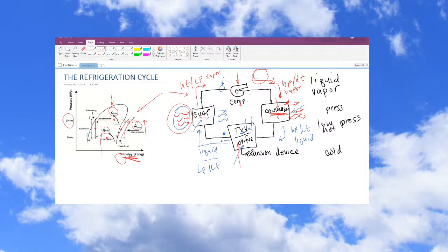Okay, so I have the compression, condensation. So if you look at this cycle here, just like it says, we got compression, then we have condensation. We're removing Q. See that right there? The Q, that's heat leaving the system, and the center here is your engine or your system. So we're condensing. Pressure is constant through that phase, just like we see here. The compressor goes through the condenser and then to the TXV, and that's where expansion occurs. So we just follow this graph here to the left, whoop, like that. And that's our condensation. That's removal of heat, constant pressure. We've lost enthalpy. And then we're going to go into the expansion valve.